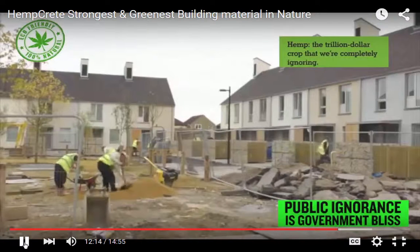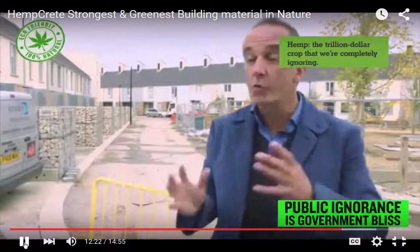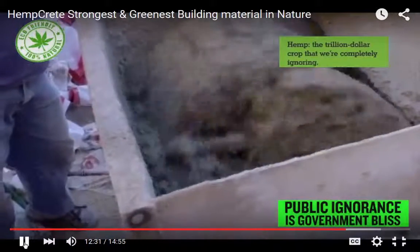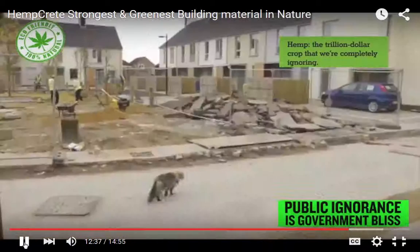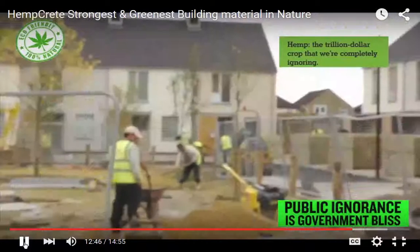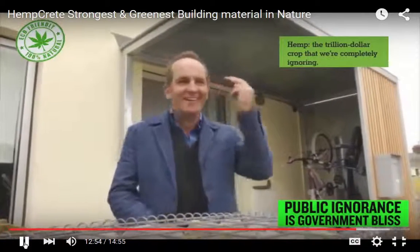The project manager here on site said to me he loved the material because we could have this lorry reversing on site, a big cement mixing lorry. Instead of pouring out heavy, wet, toxic, caustic concrete, it would instead pour out this sort of fluffy, lightweight stuff that looks like sawdust. It didn't require any power tools. So all we had was buckets and barrows and blokes. And because there are no power tools, there are no cables everywhere. It actually makes for a very healthy, very safe building site, hemp. It's a very builder-friendly material. I mean, it's a no-brainer.